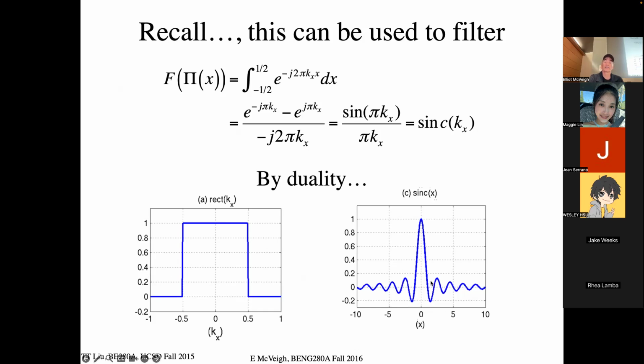So what I can do in the X domain is take this and convolve my signal with this. And it's a filter, right? So it basically blurs neighboring pixels together to give you a sum with these weights. And then all of these frequencies are gone in that signal. And so then you could sample that. And you know it's inside there.